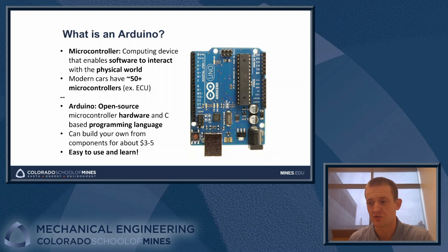There's also microcontrollers that read your wheel speed of each of your wheels individually, and they'll detect that if your car is starting to go into a skid and pulse the brakes for you. So that's how your analog brake system works. There's microcontrollers looking at how your wheels are spinning, and if it detects that you're starting to get into a skid, it'll correct for that behavior also.